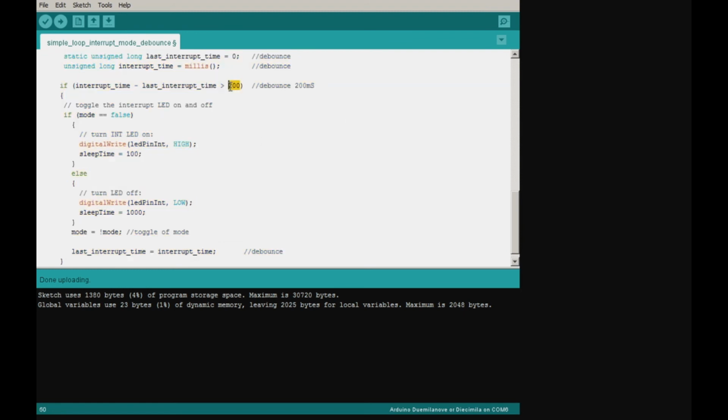with how big this value has to be. With a little bit of experimentation on the bench here, I messed around for about 10 minutes and just tried different speed button presses and what have you, and I've ended up with 200 milliseconds, and it seems to be reasonable for a realistic button press. And it's basically these 4 lines that are giving us that ability. So let's go and have a look at the hardware. As I say, we've removed the RC components and everything. We'll go and see if this code does indeed work very well.